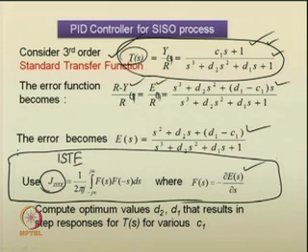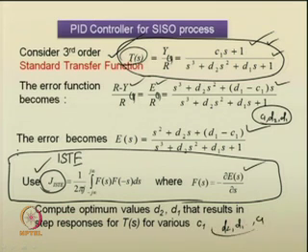How to compute the coefficients C1, D2, D1 using some minimization routine? One can easily use Astrom's recursive algorithm. Writing some simple MATLAB code, it is easy to minimize this performance index. Minimization of this performance index yields a set of D's and C1. A set of D's means all the D coefficients D2, D1 and so on, and C1 can be obtained, and that ensures us the minimum value of the ISTE criterion.